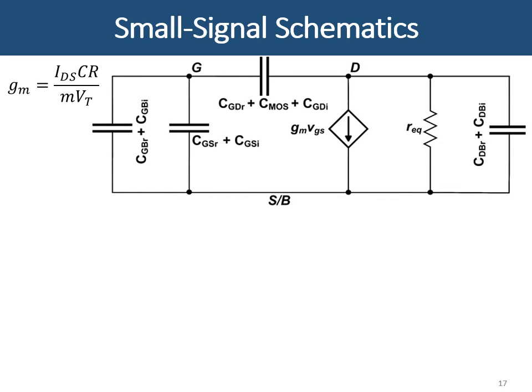A small signal equivalent schematic for linear analysis of the Y-flash device, considering various capacitors, is developed as shown in the figure. The maximum frequency of the small signal input is limited by the coupling parasitic capacitor of the two transistors. We performed spectral analysis on the modeled circuit by biasing the Y-flash in subthreshold and applying a small signal within the dynamic range. The gate source voltage is determined by the voltage division on the capacitive impedances.